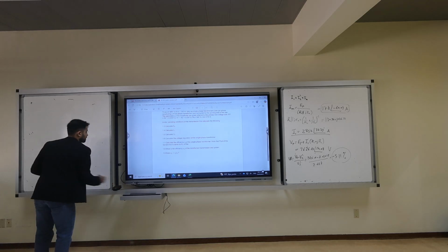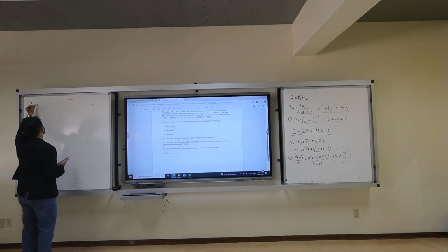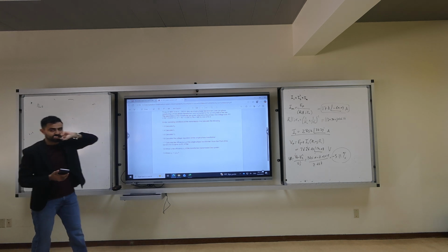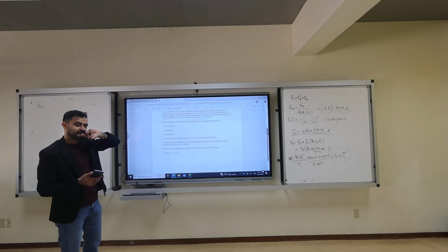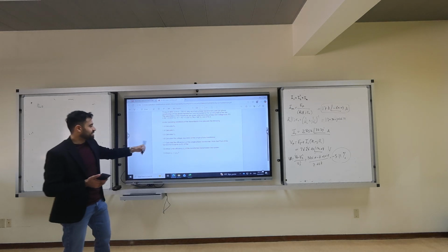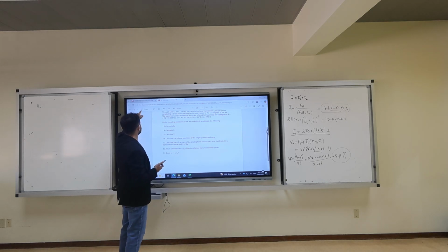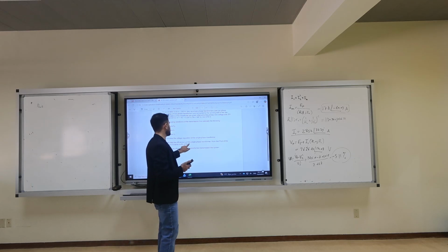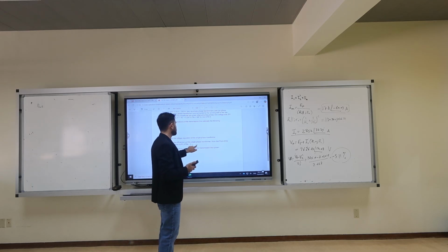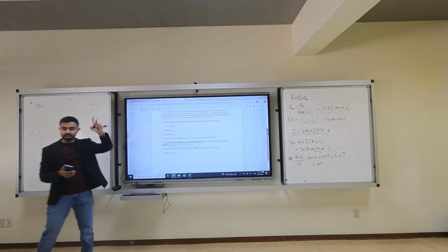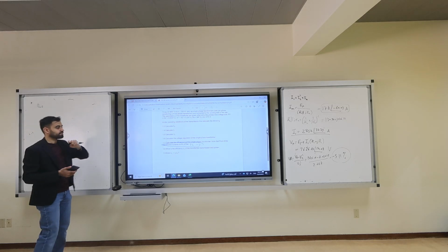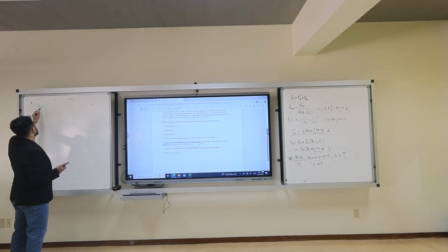What is the P input of the transformer? So note that the P out of transformer is P input of the TL divided by 3, because it is single phase. Right or not? The line is 3 phase.